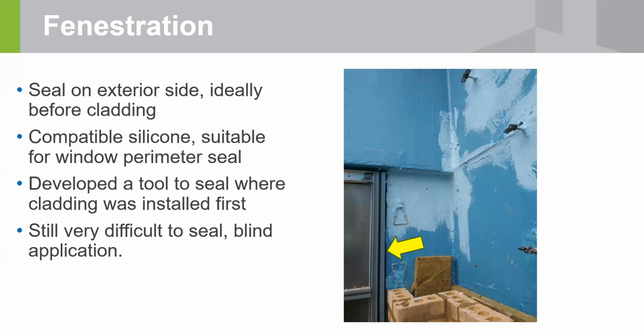And you can see there they got some of those wing nuts. Those are Posi-Tie anchors for holding up insulation, and they have a couple of holes on them where the wire ties go for holding up the brick. So this portion of the wall was masonry, and those wing nut ties are combination brick ties and insulation anchors.